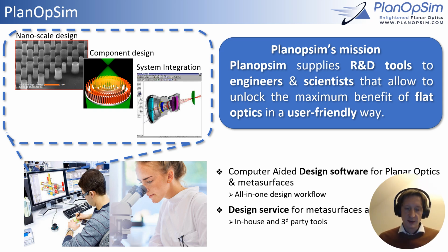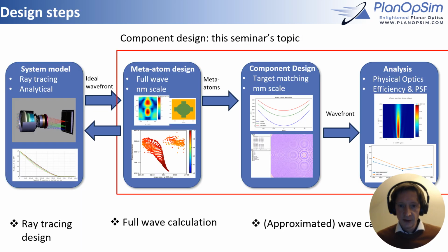And when we want to design a metasurface, it's really important that we are able to design the full scale: from the nanoscale, where we make these sub-wavelength particles that modulate and control the behavior of light, into organizing them on large components which contain millions or billions of meta-atoms, and then integrating these components, because often a single component is not enough, integrating them into systems using ray tracing tools.